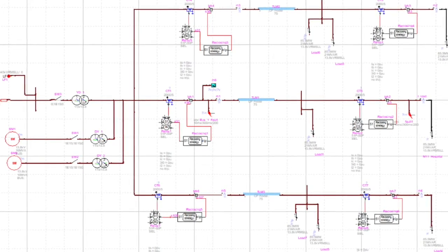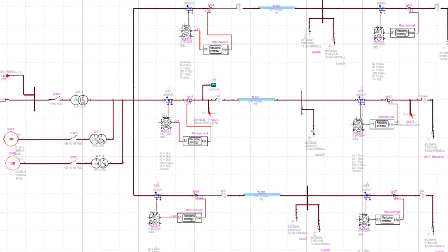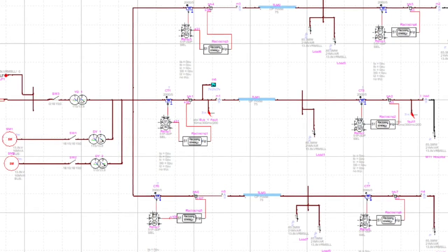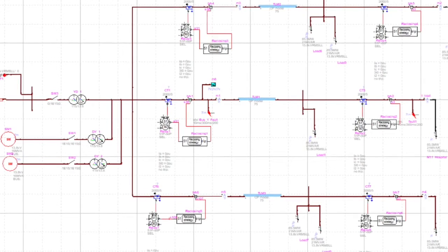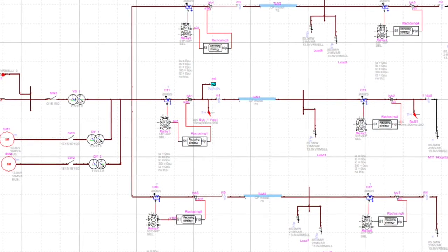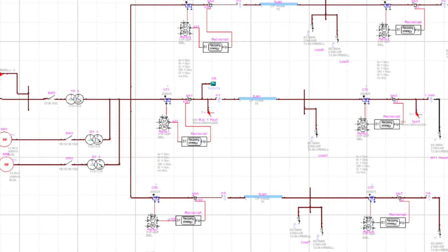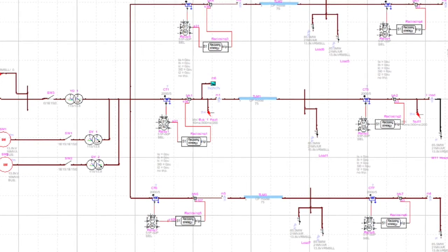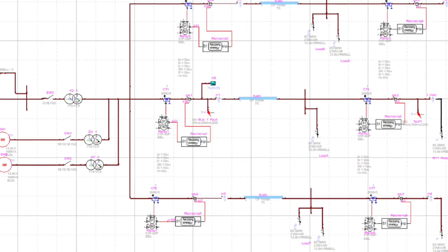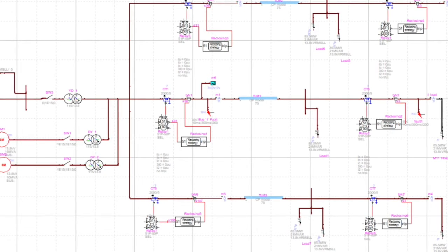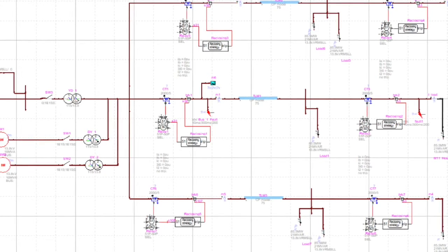A fault was also created with a time closing of 1 millisecond and a time opening of 2000 milliseconds, which can be seen here. Finally, 3 control switches were used to get better control on the generation in case of a power loss or voltage swell from switching from one source to another. For the simulation, the main time step is set to 1000 microseconds and the simulation time to 10 seconds.